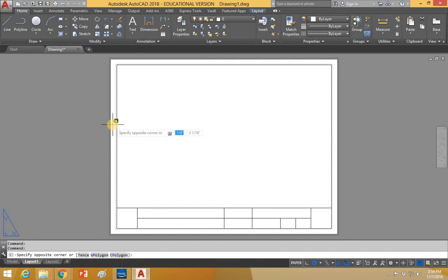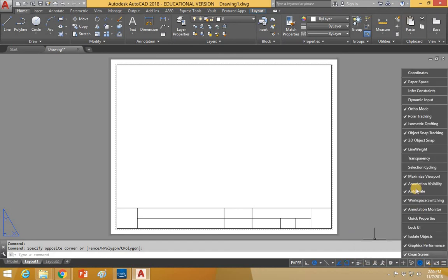And so I'm saying to myself, why haven't my line weights changed? Well, we have to turn the line weights on. Line weights can be hard because if you have these big thick lines and they're all over the place, it can almost hide other lines. So you want to be able to turn them on and off. Down here, I have this open. You might not. If you come to this bar right here, you want to make sure that line weight is checked. So if I uncheck it and then check it again, you see it opens and closes that button.